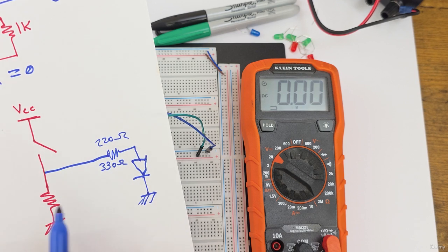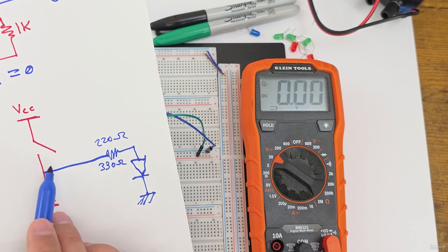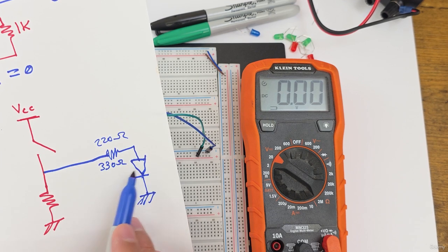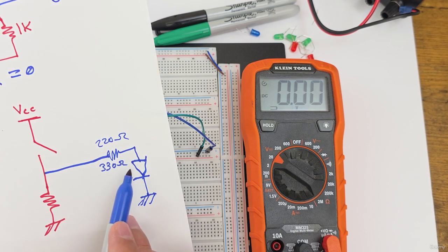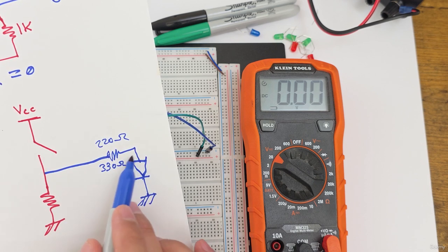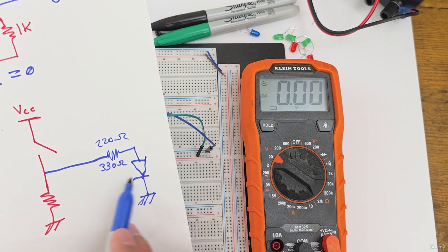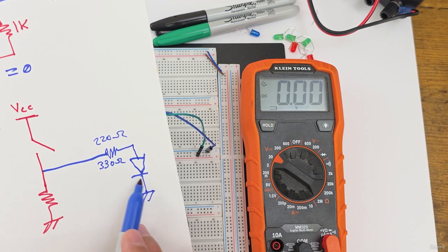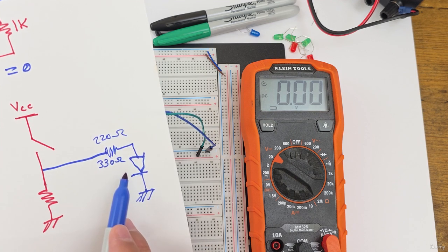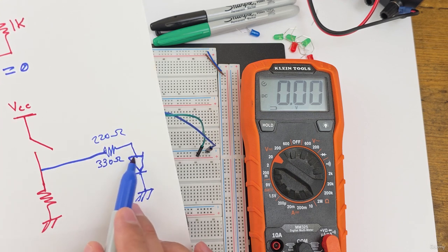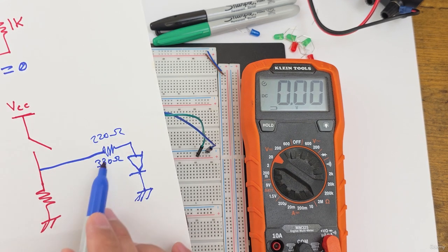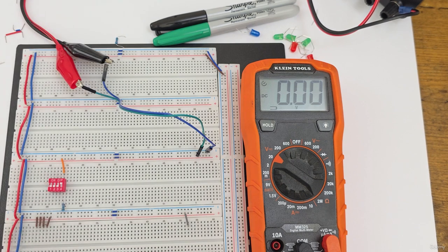But if you want to know, you just know that we have 5 volts here, 0 here, and this LED works by 2 volts. So this volt minus this volt over the resistor, you can get the current that this can take. Because if you search online, you will know how much current this takes and how much volt it works on or it uses. So 2 volt and some current. So you have the volts and you have the current. You can just divide both and get the resistor value. That is a quick explanation.